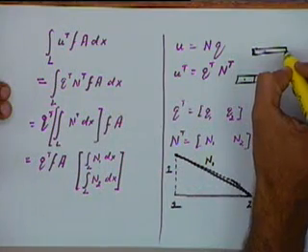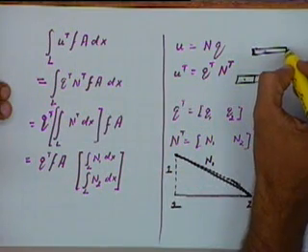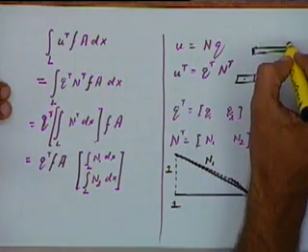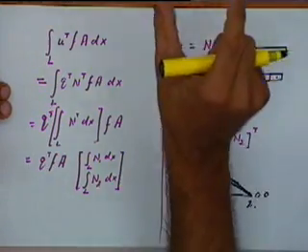Our aim is that we will take the elements small enough such that whatever assumptions we have made about this element will be valid. We have made the assumption that our displacements are changing linearly. Now that assumption will be valid only if my elements are small enough. If I take very large elements, that is probably not going to be true.